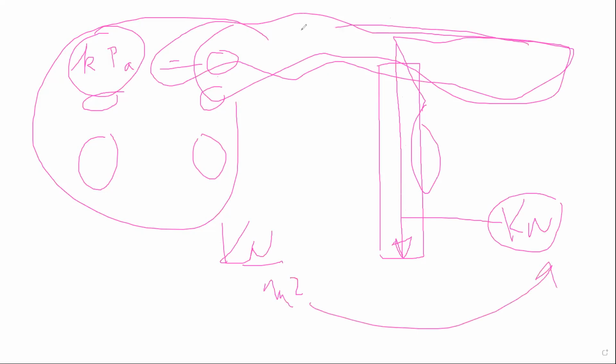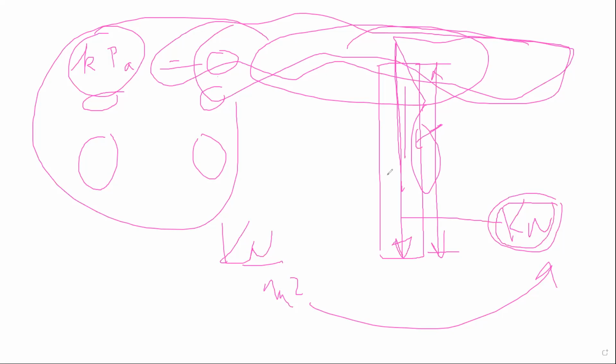I take the tributary area that this member carries, and it gives me the kilonewtons. For the weight of the wall itself, I multiplied by the height and by the tributary width of each stud, and that's how I got the weight of the wall acting on the stud. So the axial load in the member is a force, in kilonewtons. Let me clear this. Basically, in plan view, here's my wall.